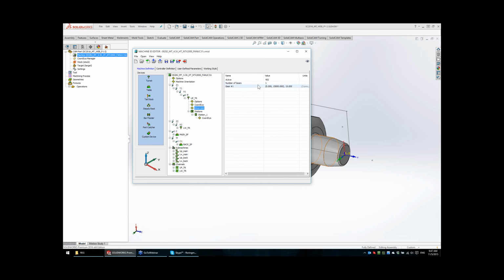We can define the gears, and also for each station we can define how this station receives the spinning unit: direct, a gear, self-drive, and we have a lot of examples, or not drive, and then from this station maybe I don't have the option of live tooling.